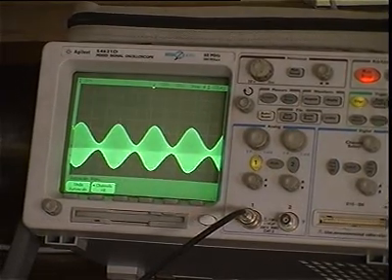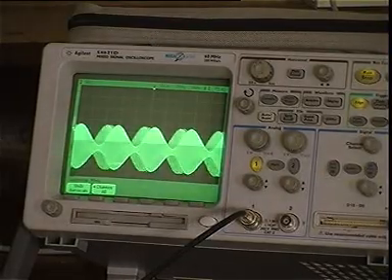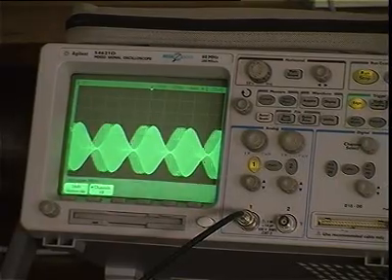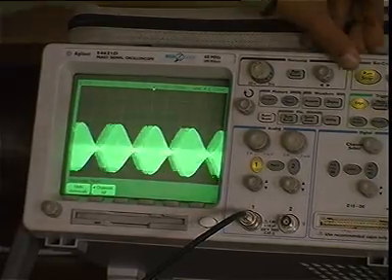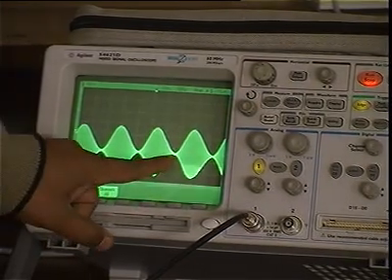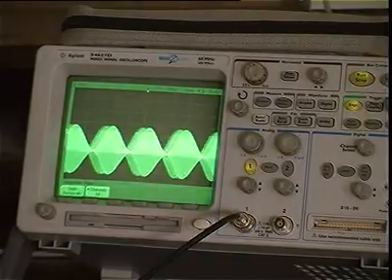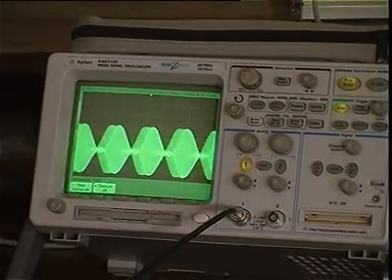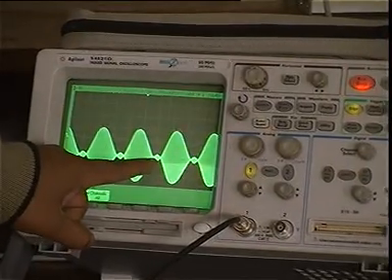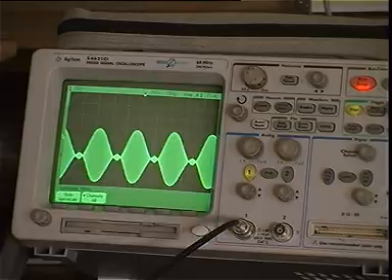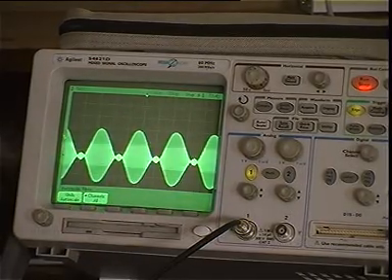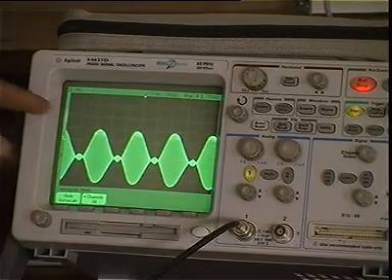At 100% modulation, what happens? This is almost 100% modulation. Okay? Look at this point. Now this is more than 100% modulation. Look at this small portion that is developing in between the two big lobes. So this tells you that this modulation has a mu value greater than 1. So this is more than 100% modulation.